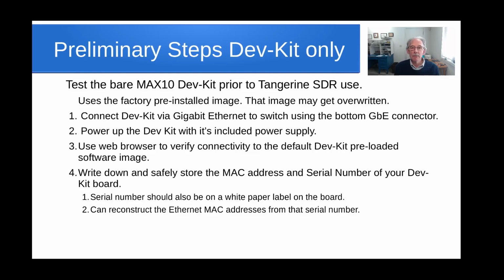It comes with a pre-installed image that will become overwritten as you deploy your development image. You'll power up the dev kit with its included wall-wart power supply and use the web browser to verify connectivity to the default dev kit preloaded software image. All of these are steps that are documented with the manual that came with the dev kit itself.